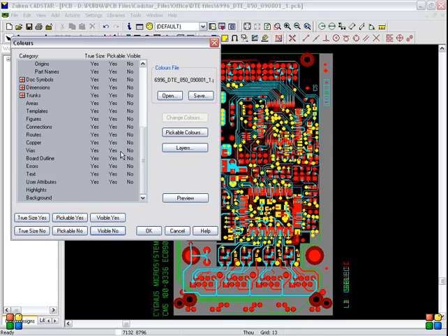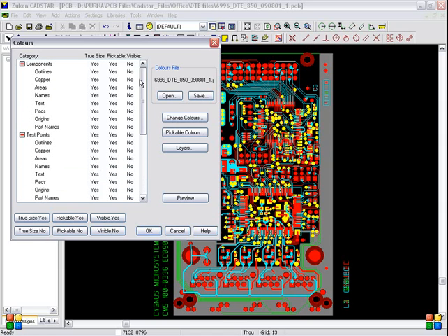And now you can start the process and go to the top level, and you have to click here components category, double click yes, outline yes, and next names yes, and after that come to the test points category and visible as the test points category and double click here and outlines yes and names yes, and come below and